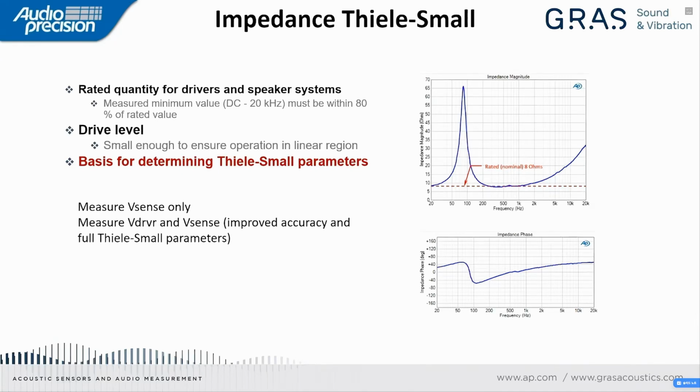Thiele-Small parameters. In APX software, we usually have a couple of options for measuring impedance. You can measure the voltage across the sense resistor only, or for better, more accurate results, you can measure voltage across the driver and the voltage across the sense resistor for improved accuracy and full Thiele-Small parameters.